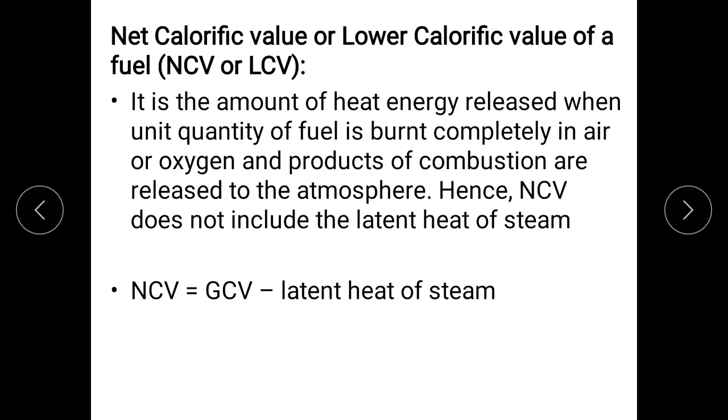The major difference between gross and net calorific value: in gross calorific value, in addition to the calorific value of the fuel, you are getting extra heat due to the condensation of steam. Whereas in net calorific value, it is only the calorific value, because it doesn't include latent heat of steam. Here we are releasing the products into the atmosphere.